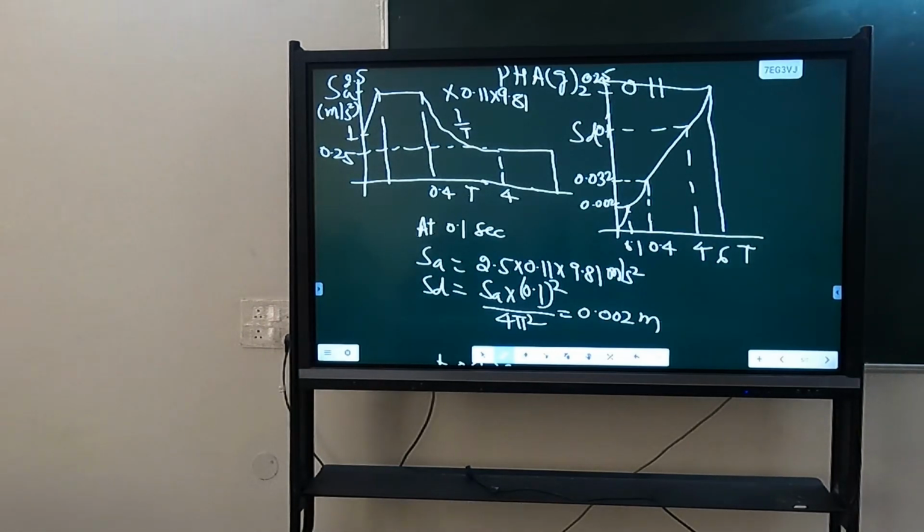Mean is, why am I giving mean? Because you will look for sigma level. So mean and mean plus sigma. The mean value is not the mean of all the sources. Mean is the mean of the attenuation relation. The attenuation relationship itself gives you, for one source, mean and sigma. This is a simple attenuation relationship, it does not give you sigma. It gives you only mean. That's why I have written mean, and that is what we will be using for analysis.